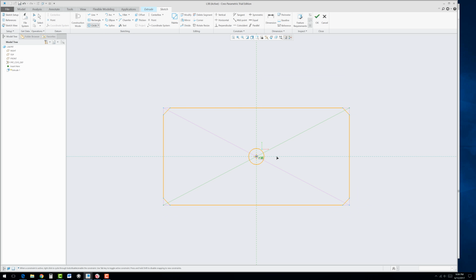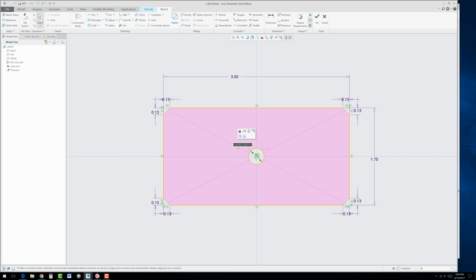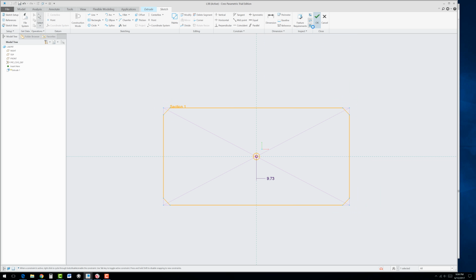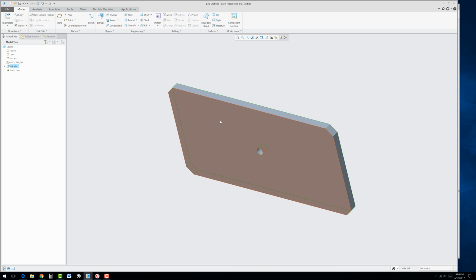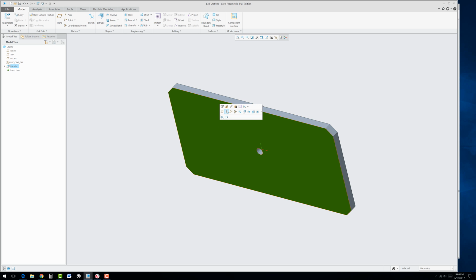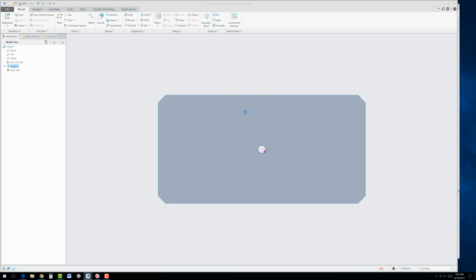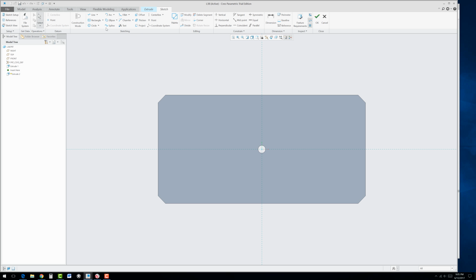Now we could go ahead and we could also put the through hole in. And that, remember, is not on the print. My apologies, 0.125. You'll find mistakes like that in my work from time to time. Okay, now we could go ahead and hit OK, and it is 0.125 thick. Hit apply. Now we could select this face and go to extrude and mimic what we did last time with the center rectangle tool. I'm going to go ahead and draw one of them over here.